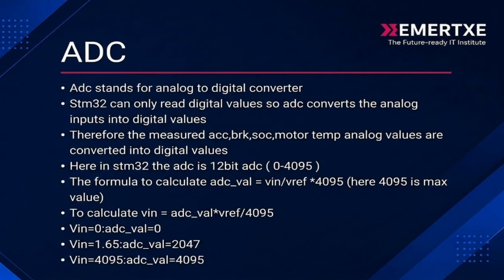In this slide, we learn about the ADC, analog to digital converter. The STM32 can only read digital values, so the ADC converts the analog inputs to digital values. Therefore, the measured acceleration, brake, SOC, motor temperature, etc. analog values are converted into digital values.